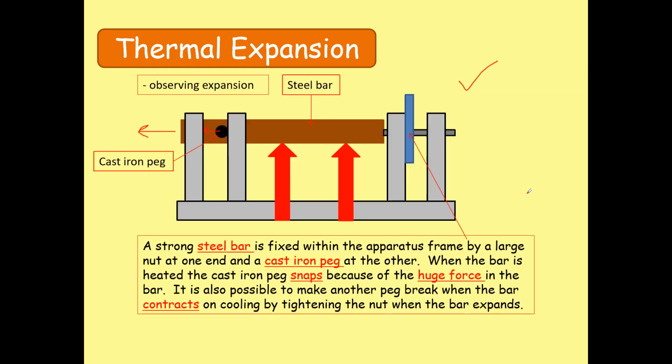So you need to understand that, as we discussed previously, the coefficient of expansion needs to be understood. If we create any structure using any material, and we don't account for the thermal expansion, then in summers it may cause collateral damage of some sort, some structural damage due to expansion, right? So this is a very important factor to note, that matter expands when heated up. If it's a high temperature application, we need to account for the thermal expansion, and we need to give gaps like these to allow for thermal expansion.